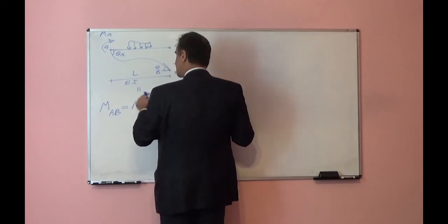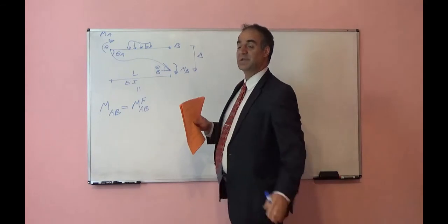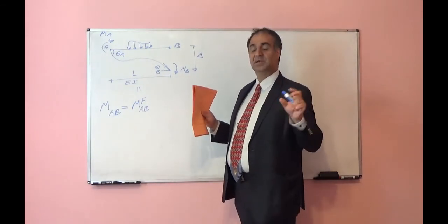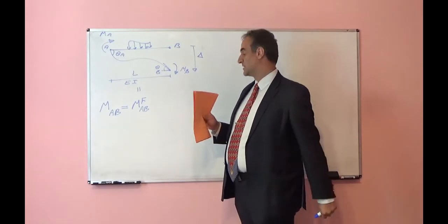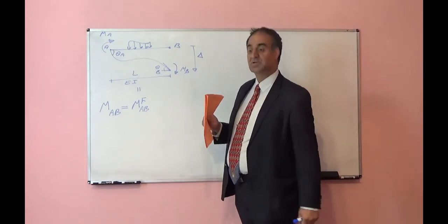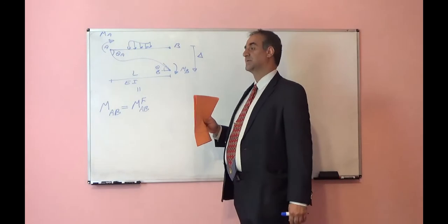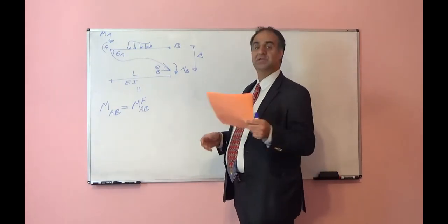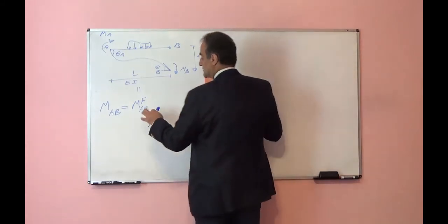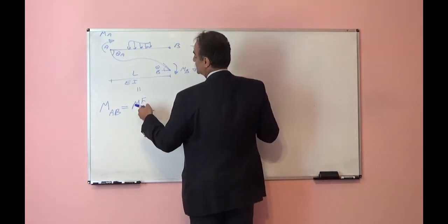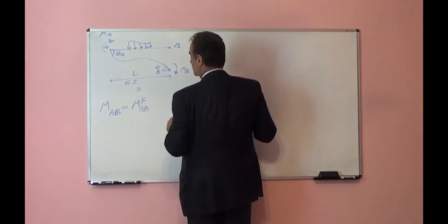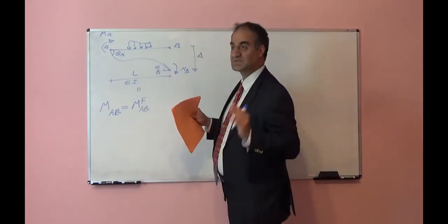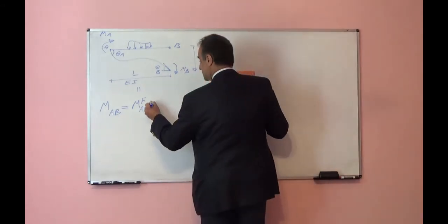I will find that when we assume both ends are fixed and only we have external load, we can find the moment for support using the force method. Before, a lot of researchers found it and developed tables. We will use those tables, but you can find them yourself too. So M fixed AB means the support moment because of external load whenever we assume both ends are fixed, plus